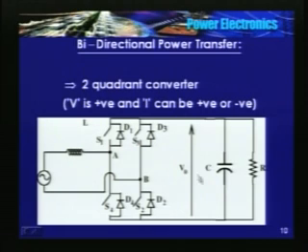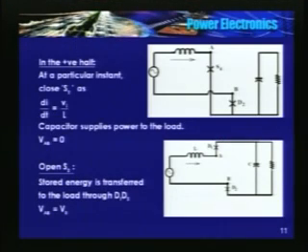We have a large capacitor here, whereas current can change. I can have a bidirectional current, hence the name 2 quadrant converter. Same thing, in a fully controlled bridge voltage can change, current cannot change, whereas here current can change, voltage cannot change. Okay. Let us see how it works. First cycle, case 1, first cycle, positive half, depending upon the control strategy, you close S4. S4 only. So what happens?